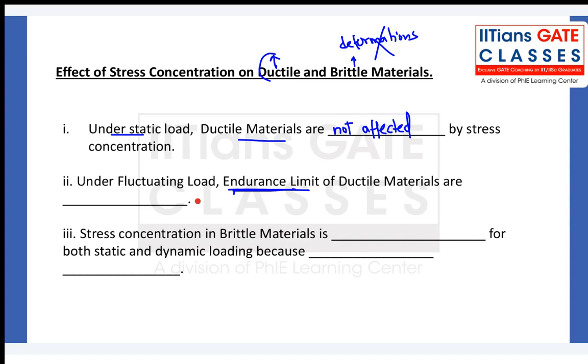So the endurance limit of ductile materials is highly reduced. That is why we have to study stress concentration for fluctuating load.